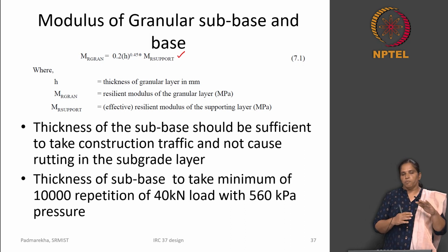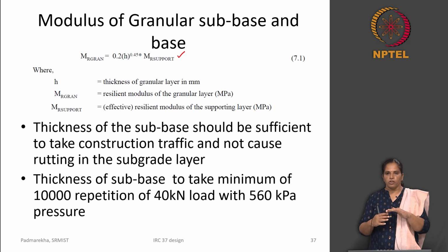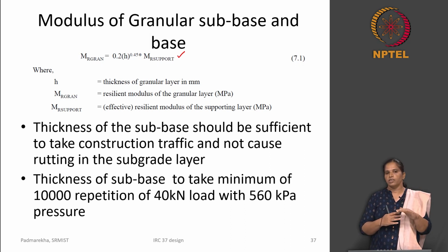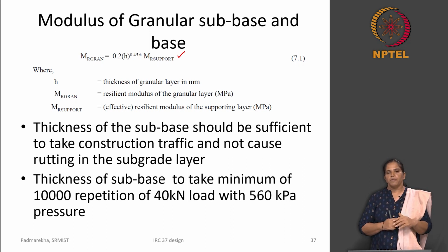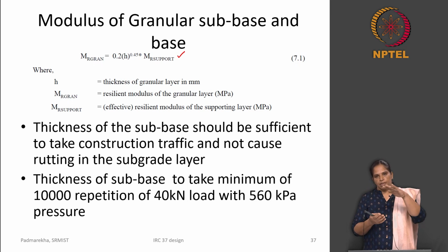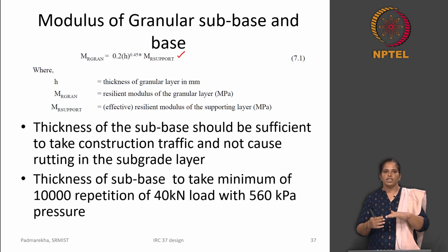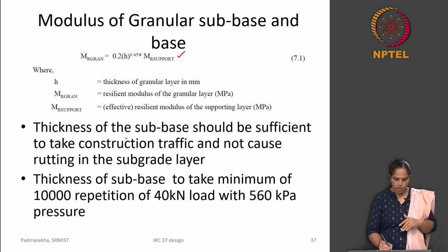Now, if both base course and subbase courses are made out of a granular layer, you can consider both to be the same single layer and compute the modulus here. But one thing we have to ensure is that the subbase we are providing above the subgrade layer should be sufficient to take the load and prevent rutting of the subgrade layer during the construction process.